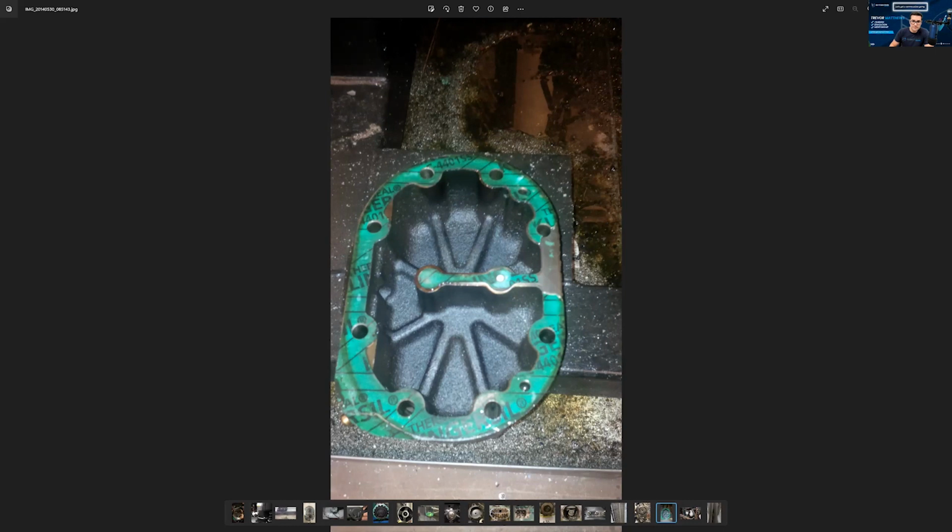Well, with that gasket you're showing there, that's blown. And if they've determined that the compressor doesn't have enough damage to replace, they have to put a new gasket in place. We would always recommend no kind of gasket sealers or any of that kind of stuff, just a very thin film of oil. And usually it wouldn't be the POE oil. That's not going to be good on your skin, but just a very thin film of mineral oil on each side of that gasket. And then the proper torque specs in the proper cross pattern is also very, very important. That calibrated forearm, as we would jokingly say, is not enough to truly do a proper torque on those. And the manufacturer is very particular about that.